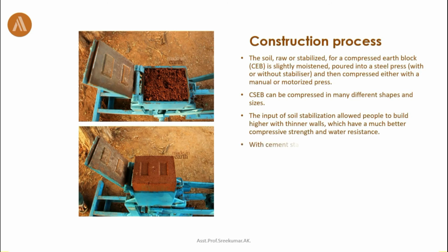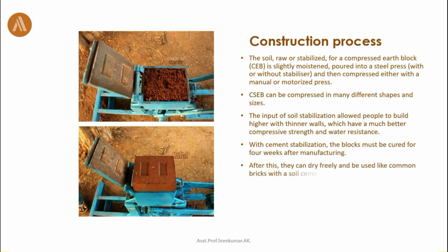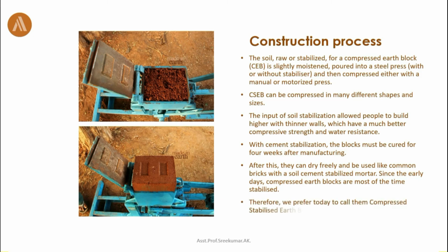With cement stabilization, the blocks must be cured for 4 weeks after manufacturing. After this, they can dry freely and be used like common bricks with a soil cement stabilized mortar. Compressed earth blocks are most of the time stabilized, as shown in the examples hereafter. Hence, we prefer to name them compressed stabilized earth blocks.